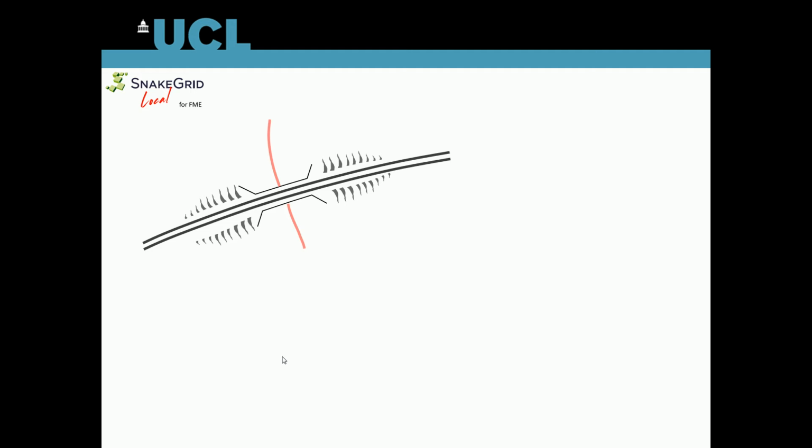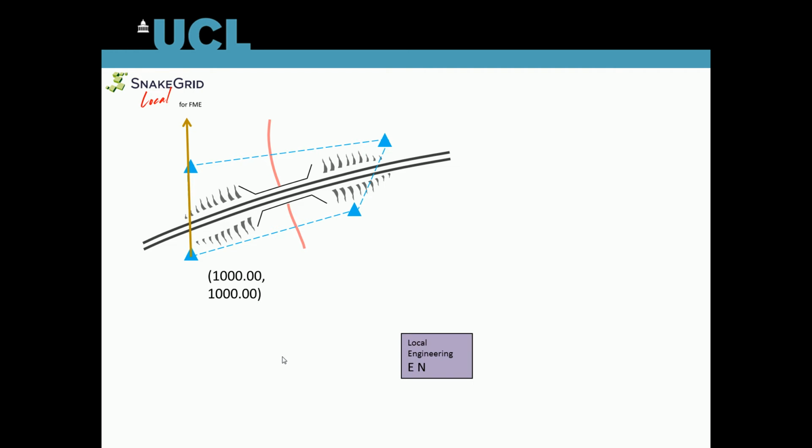It's quite common practice in engineering to devise a local coordinate system, maybe by introducing control points with one of them assigned to the role of a datum and given some rounded set of coordinates, maybe another direction to another point assigned as an orientation. And then you carry out a quick survey, a little survey of those points by traversing and so on to assign coordinates to those control points. What you've established there is a local engineering system.